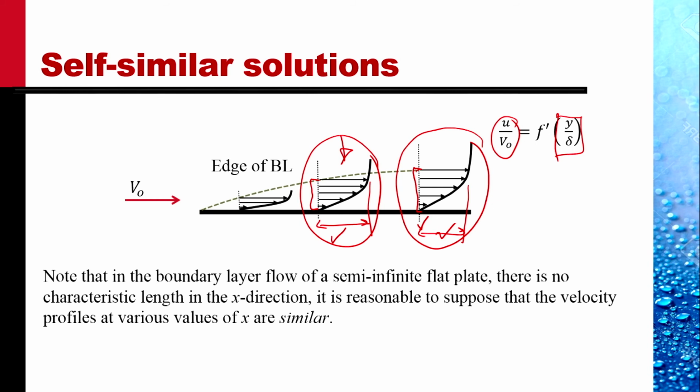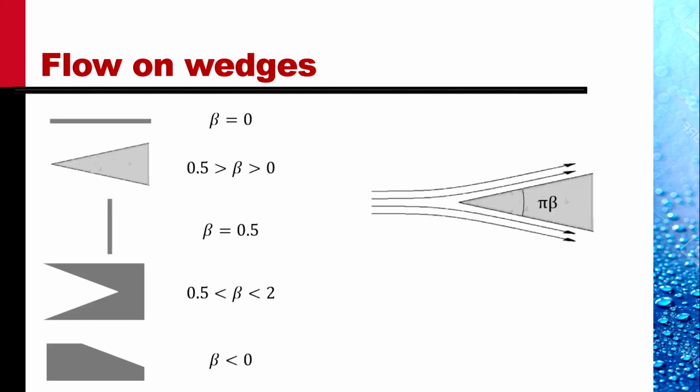And so the characteristic quantity of one variable is determined in terms of the value of the other variable. It is not just on the flat plate, but flow over wedges are also self-similar. Falkner and Skan obtained the conditions under which the flow could be similar. And they said flow over wedges is one case where the flows are similar.